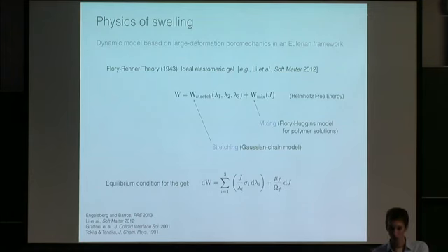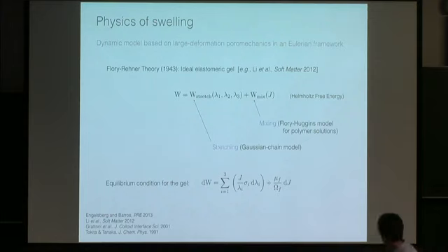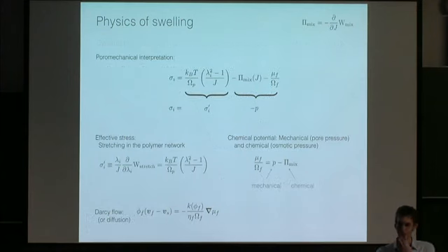And so when we do this, what we get is something, oh yeah, sorry. The lambda, were the lambda? Oh yeah, so lambdas are stretches. That's important. You can think of the lambda as a strain, essentially. It's not quite a strain. It's sort of like 1 plus a strain. So lambda equals 1 is the undeformed state, and lambda greater than 1 means you're stretching it. Lambda less than 1 means you're squishing it. And the lambda squared are the eigenvalues of F. But just think of it as strain. It's easier. Subscripts are directions? Or?